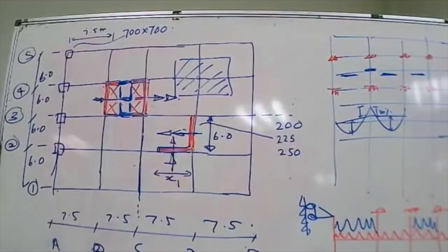I will ensure that, because we are not saving a lot of steel by finding the exact cutoff point. We are not saving a lot of steel. Okay, sir. The reason for asking that question is we don't know how it can affect the service criteria. No, basically, if you continue the reinforcement, then there's no way the service criteria will be affected.